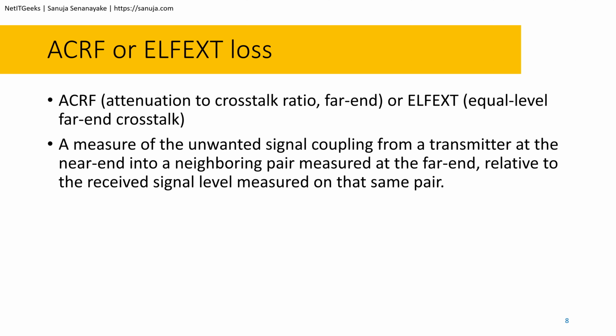So a critical consideration in determining the capability of a cabling system is the difference between insertion loss and the near end crosstalk (NEXT) loss, right? The difference is known as the attenuation crosstalk ratio, also known as ACR. Positive ACR calculations mean that the transmitter signal strength is stronger than that of the near end crosstalk.